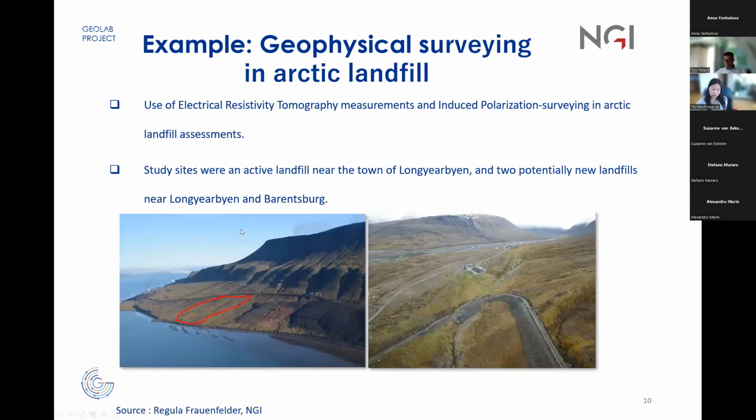I will move now to very briefly another example of a very different type of study, where we use geophysical surveys to study Arctic landfills. In this case, at the study site shown in these pictures, we use electrical resistivity tomography measurements and induced polarization surveys to assess the performance of Arctic landfills. The study site involved an active landfill near the town of Longyearbyen and 2 potential new landfills near Longyearbyen and Barentsburg.